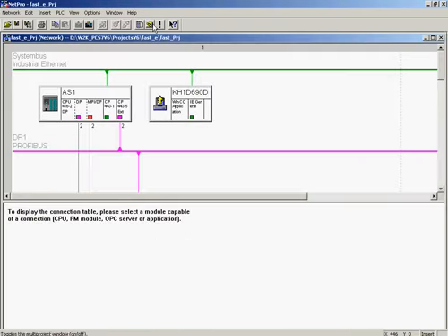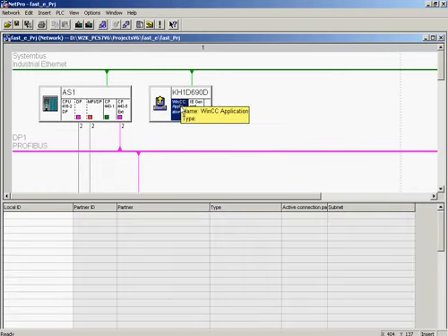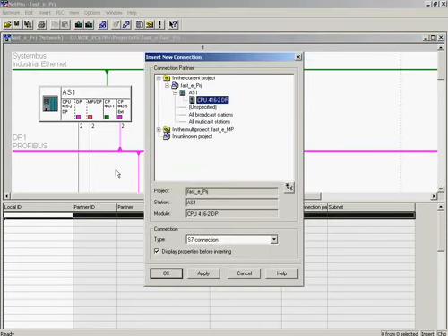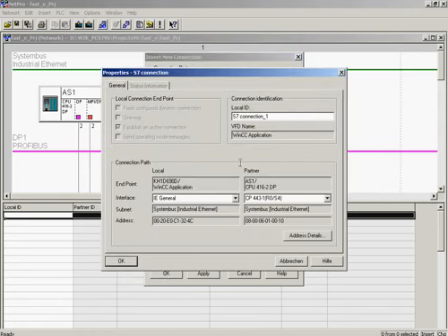NetPro is started. In order to define the named connection, the WinCC application is first selected in the schematic station. All existing connections are displayed in this table. A new connection is created by double-clicking on an empty cell. This is the CPU to which we want to define the connection. In the Properties dialog, the name of the connection is changed to OS1 AS1. No further information is required.